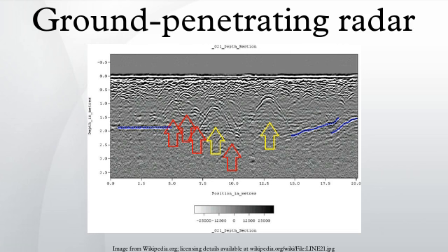The depth range of GPR is limited by the electrical conductivity of the ground, the transmitted center frequency and the radiated power. As conductivity increases, the penetration depth decreases. This is because the electromagnetic energy is more quickly dissipated into heat, causing a loss in signal strength at depth. Higher frequencies do not penetrate as far as lower frequencies, but give better resolution.